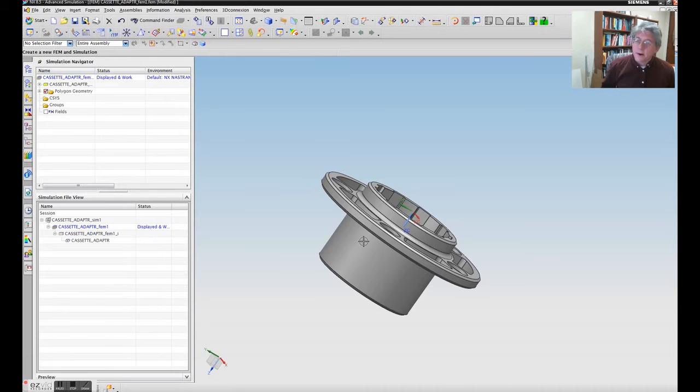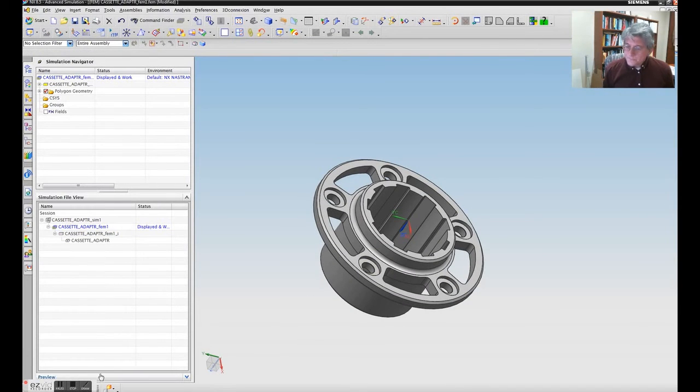So, take a moment to look at that. Get used to moving back between the different windows. You can also do that through Window up here. There's the sim, the part, the FEM file, and the original part file. So all four files are here: the original design part, the idealized design file, the simulation, and the FEM file. Once you bounce back and forth between all those, you actually have to save all of them separately, so that can get a little annoying, but it's a good thing to try and do.